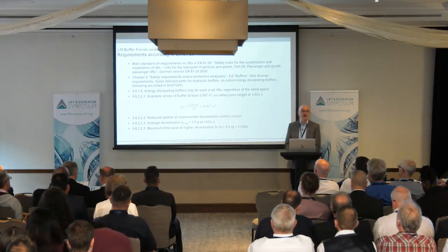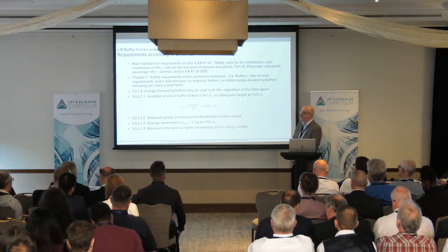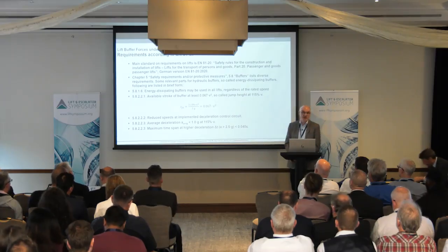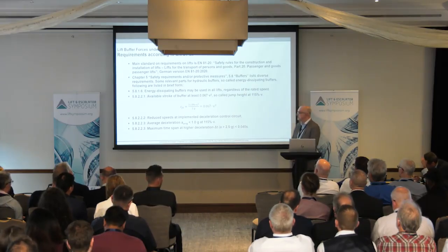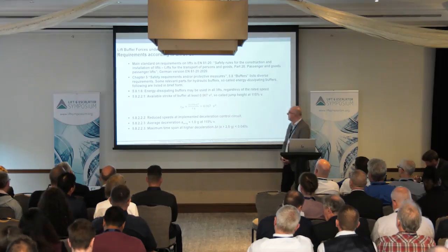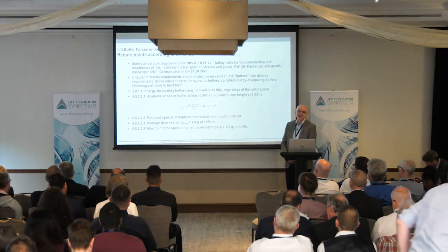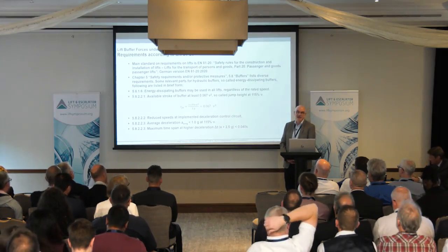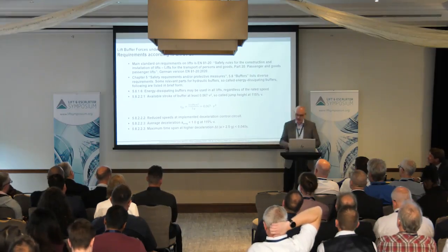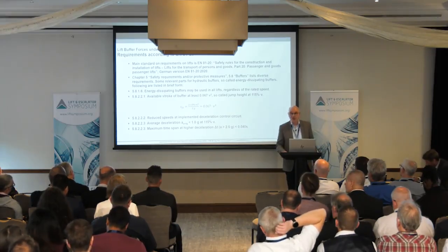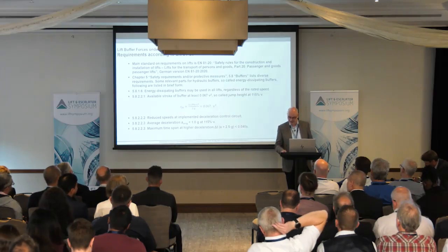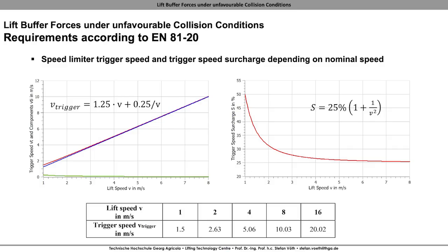And as I already learned, this is a so-called jump height in English. But this is not the only requirement. There are further requirements. The second is an average deceleration less than g at this impact speed, and a maximum time span of 40 milliseconds for accelerations higher than 2.5 g. And all these requirements have to be met. For me, maybe there's the question in which cases they have to be met. But maybe you don't know.